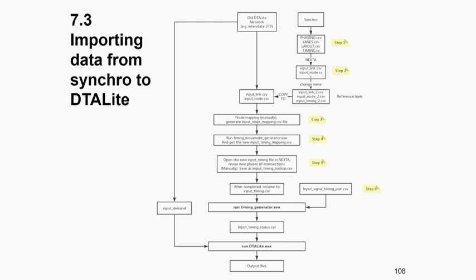Number 1, Synchro and the main DTALite network actually have totally different coordinate systems. They may have totally different movement configurations. They may have a different coding schema. One is in this layout, lanes, and phasing.csv UTDF format. One is in our much more streamlined data format. So how to merge them together is a challenge. But we hope that by merging this information piece by piece, eventually we can encourage a universal signal data format representation for the whole city or for the whole state.